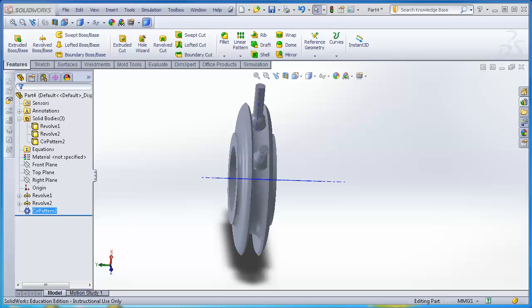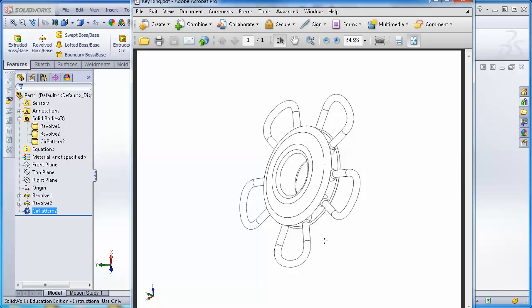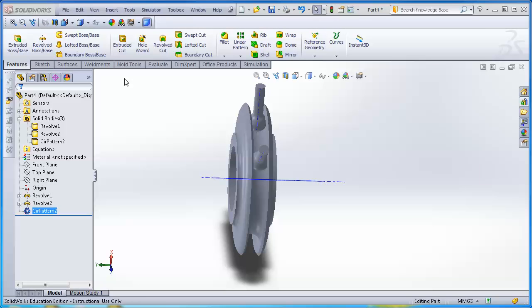Now what I want to do is turn that object, with a little bit more work, into this object, which is the revolve ring unchanged, these pieces unchanged, the angle changed, but I want to put a sweep connecting each 2 of them, and then I'm going to take this pattern and pattern that around the object. So let's go do it.